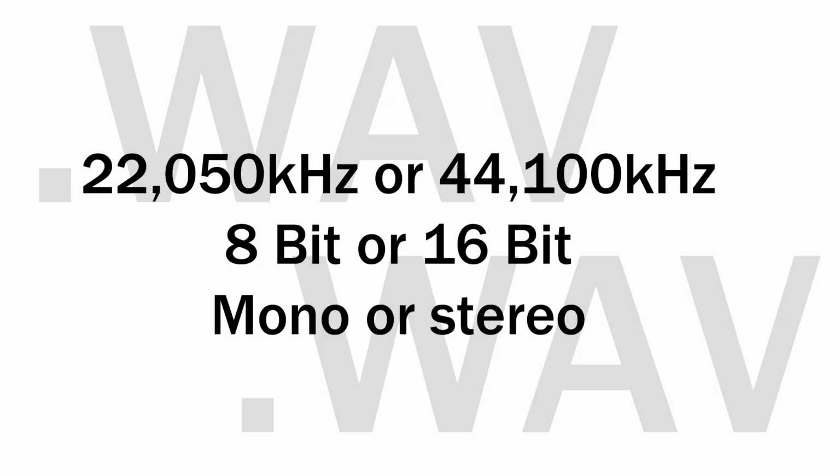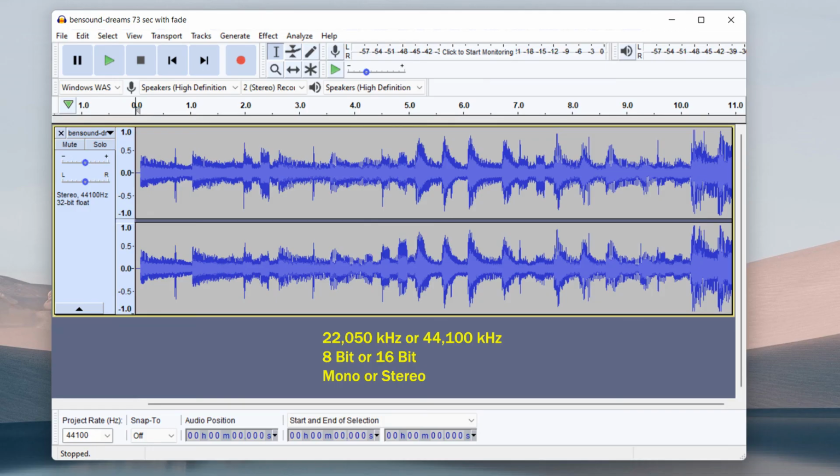The last thing I'm going to look at is sound files. You can use your own WAV files in Sound Teacher, provided they meet the following. And the Sound Teacher always converts the sound file into the format 44 kHz 16-bit mono. To get a good sound, the WAV file should be in this format. I use Audacity, the free sound editor, on the Beier software stick, or you can download it. It's a great bit of software.